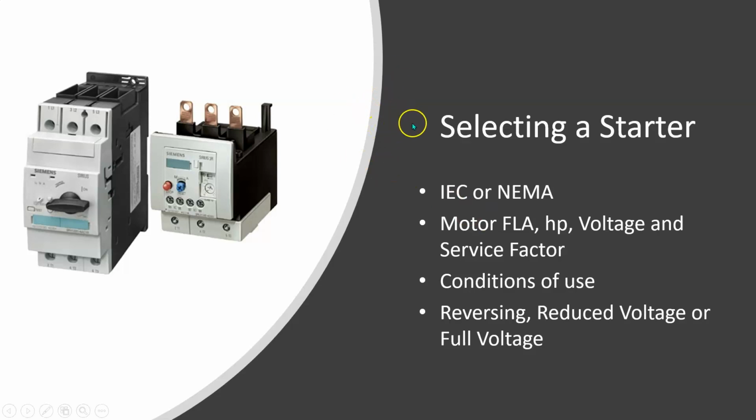Alright, so talking about selecting a proper starter. Right, so you're going to have to look at, okay, do I want IEC or NEMA? Again, NEMA is what we'll be using in lab here and in North America most likely. NEMA are larger, but they're more versatile. You can use them for a wider range of purposes. Compared to the IEC, they're more made for specific jobs.